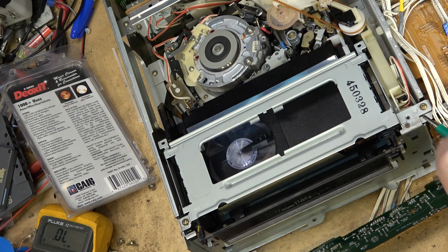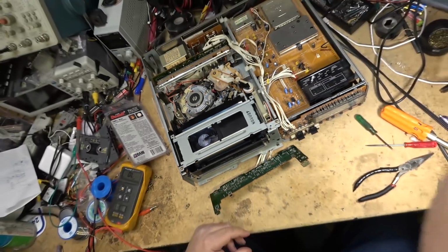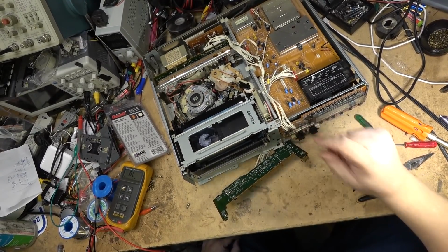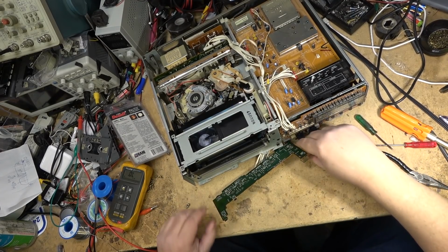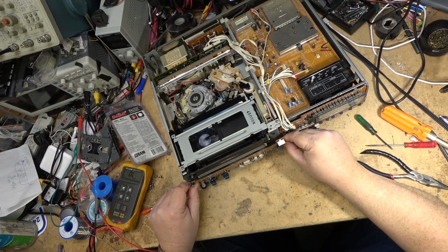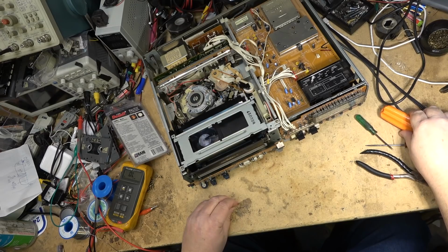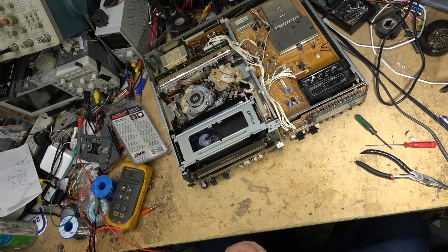Let's remount the board. The hi-fi audio problem might not actually be a problem. It might have been that the person who recorded this tape had the audio record level turned all the way down to minimum, or they may have had the machine in simulcast mode, because believe it or not, people did that, and it happened more often than you would ever think possible.